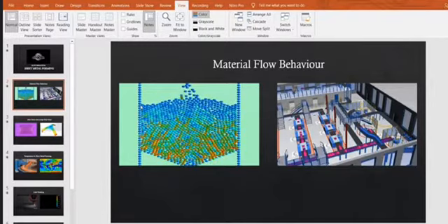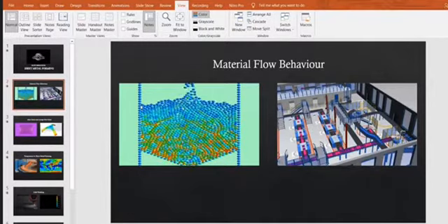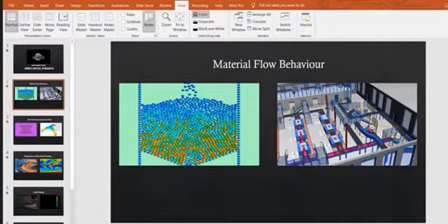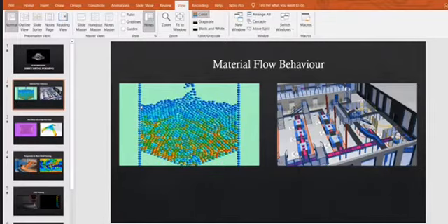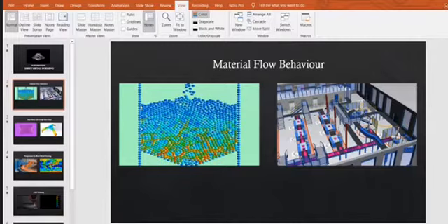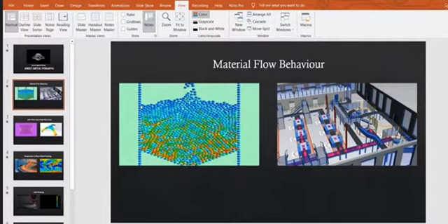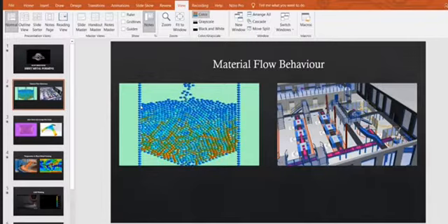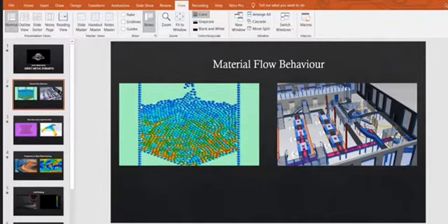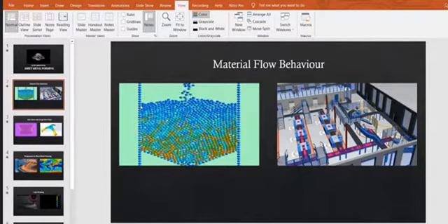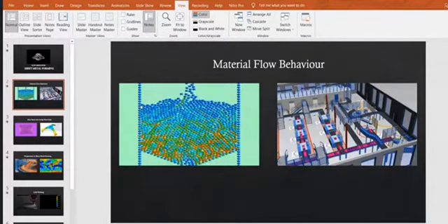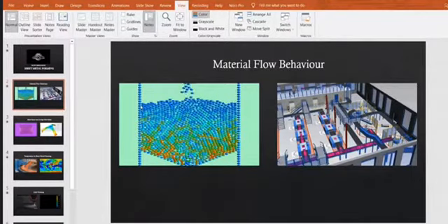The typical stress-strain curve for most metals is divided into an elastic region and a plastic region. In metal forming, the plastic region is of primary interest because the material is plastically and permanently deformed in these processes. The typical stress-strain relationship for a metal exhibits elasticity below the yield point and strain hardening above it. This figure, true stress-strain on a log-log scale, indicates this behavior in linear and logarithmic axes.